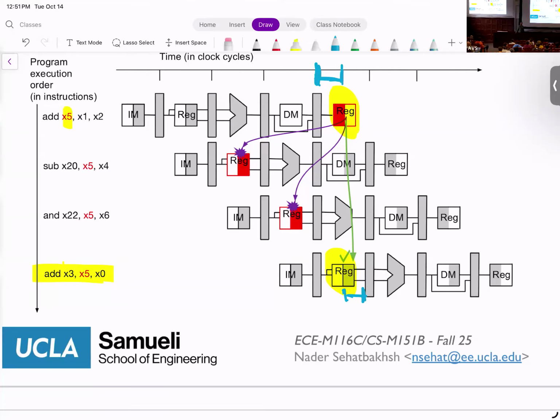Yes. So someone asked about this pattern of half cycle. This is enforced in hardware, and the answer is yes. All you need to do is make sure that your write delay is less than half of a cycle, and your write is synchronized with the clock. That's how you do it.